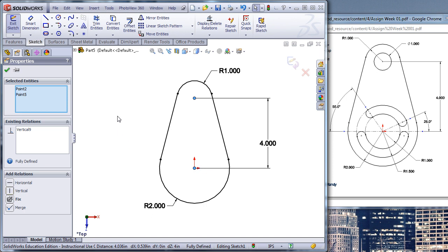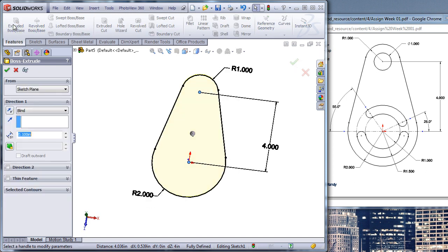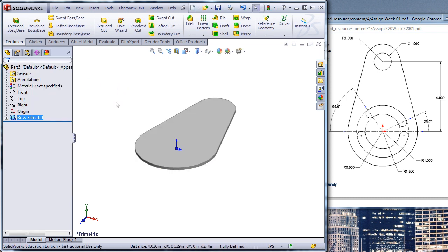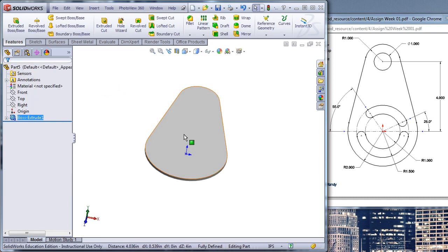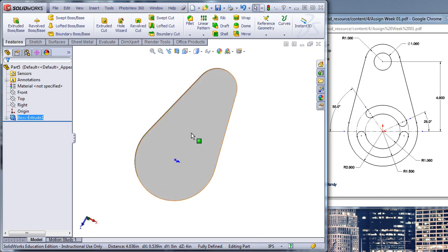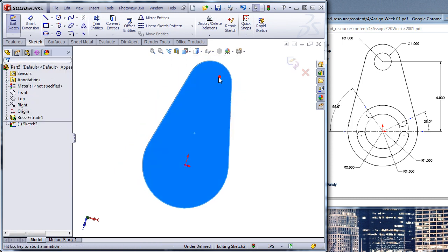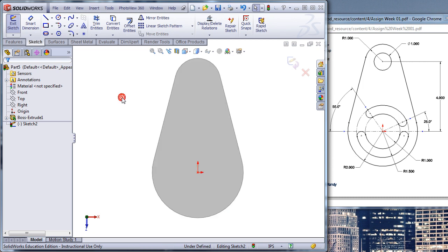I'm going to extrude that 1/8 of an inch thick. That's in your directions. So feature, extrude, 0.125. And we'll hit OK. All right, so there's my outside shape. I'm going to click on that front face, start a sketch. Let's go normal 2. Whoops, I don't want a section view. Normal 2. We're looking straight on.